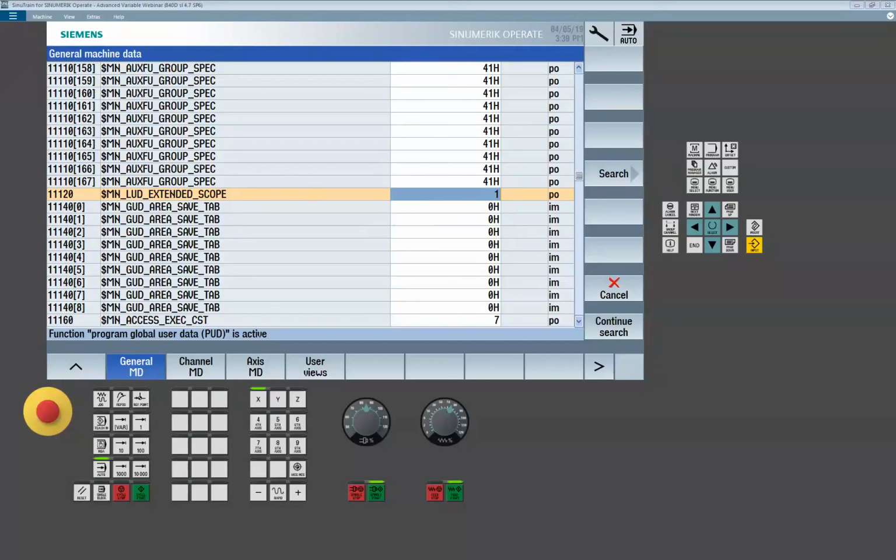Okay. Can you use the PROC save for the unit measurements, force a subroutine? Yes. So here, Dan is asking if we're using the save command, will it work for my unit of measure scenario? And it certainly does, right? Because it's all G-code commands, and G700, G710, G71, they're G-codes.